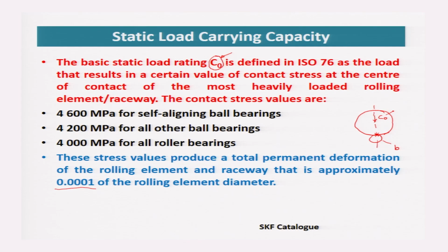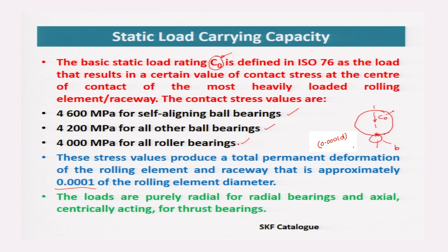Well, so when you are applying this C0 static load which is producing deformation equal to 0.0001 d, the diameter of the roller or ball, then the amount of contact stress that is permissible or that is produced is this one for the self-aligning, this one for the ball bearing, and this one for the roller bearings.